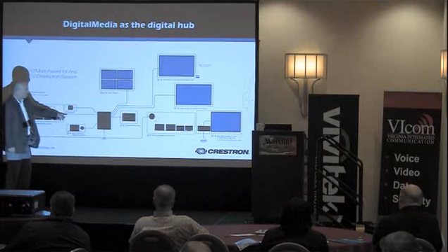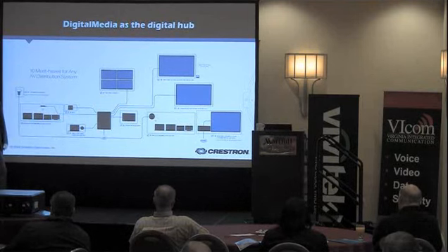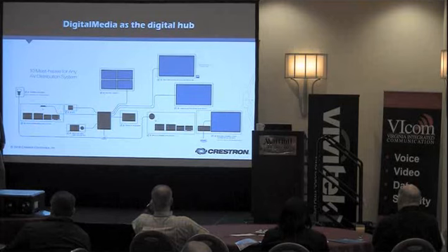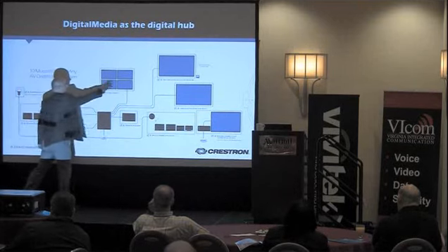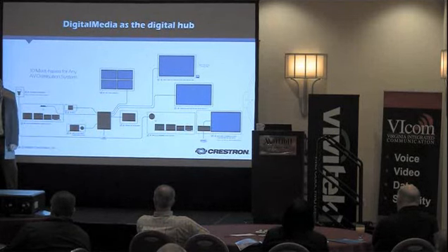I've got 4K input, which we've been talking about, and then zero latency connection points, meaning digital media inputs for bring your own device. Video wall capability coming into digital media. I could have a quad screen split using some DM cards. Preview on a touch panel using the HDMI out, or streaming if you want, using an H.264 signal.